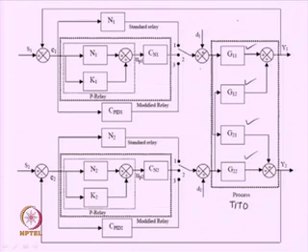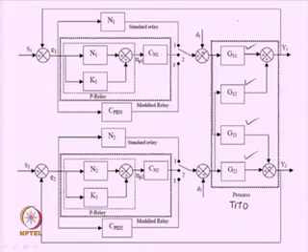Okay. So, initially how will it be conducted, how to start with, where we have shown some standard relays also in the block diagram. Initially connect two standard relays and get the limit cycle outputs, and based on the limit cycle outputs use some simple formula technique such as the technique given by Ziegler and Nichols. Those techniques can be used to find the parameters of the controllers, CN1 and CN2, which are nothing but the PI controllers.